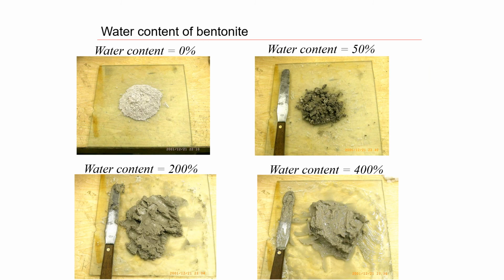You will see that water content can actually be very high. For most soils in nature, water content will be from about 20 to 30-40%. But for very expansive soils, very reactive soils like, for example, bentonite, water content can actually exceed 100%, and it can be up to 400%, as you see here.